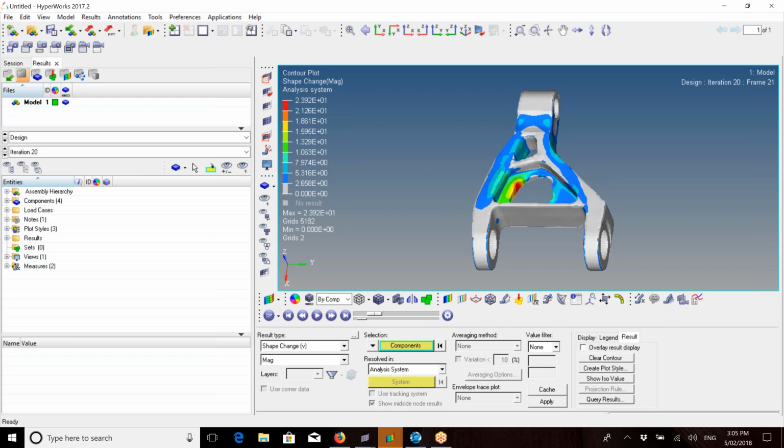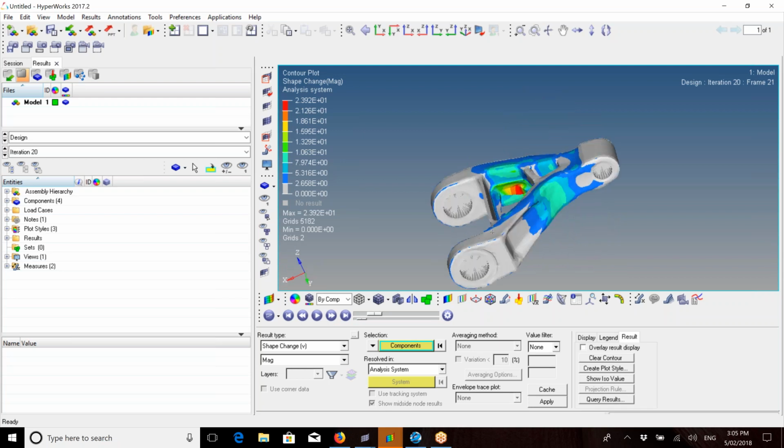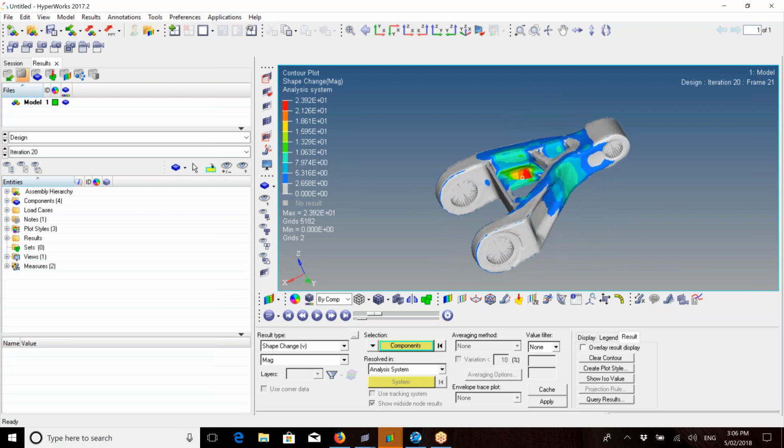You can say the maximum frequency coming in or the minimum frequency coming in will be this, and the optimization will then design around that to make sure that this part that you're optimizing doesn't see those modal frequencies, so you'll never hit resonance. And because that is actually a very vital case, as it is considered the first mode of failure.